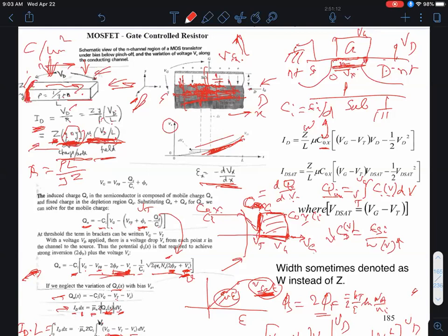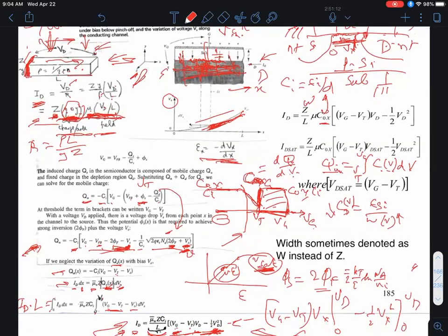We see, of course, that for a P-type substrate, so it's P silicon, because I'm looking at N MOSFETs, for negative gate voltages the holes are attracted to the surface, so I have an accumulation layer, and therefore a MOS capacitance equal to CI or Cox. But as I make my gate voltage more and more positive, I start pushing away the majority carrier holes. I start forming a depletion region in series with the oxide capacitance, and therefore the overall capacitance keeps dropping until you reach the maximum depletion width corresponding to a band bending of 2 phi f, twice the Fermi potential.